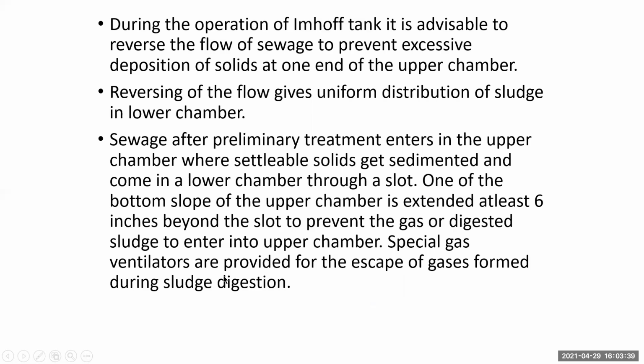During the operation of Imhoff tank, it is advisable to reverse the flow of sewage to prevent excessive deposition of solids at one end of the upper chamber. Reversing the flow of liquid gives uniform distribution of sludge in the lower chamber.